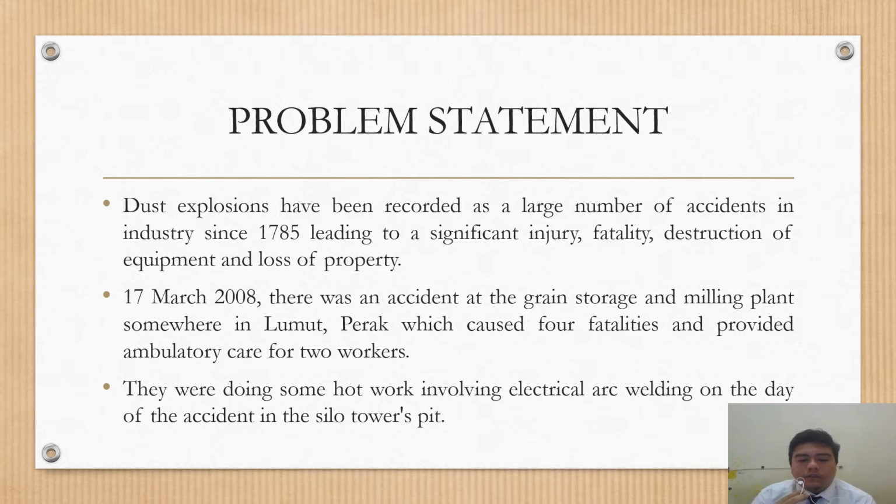The welding was placed on one of the transfer lines of grain between the interconnected conveyor and the elevator in the silo tower. 2 elevators of the 4 elevators in the silo tower were installed on that day to move the raw grains from the silos to the other parts of the building. It is highly believed that the explosion, accompanied by a blinding flashlight observed by the staff in the plant's control room, originated from the basement level, causing extensive damage to the silo tower facility.